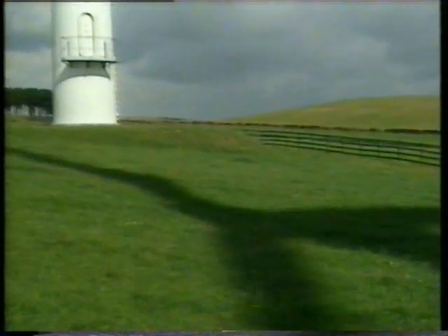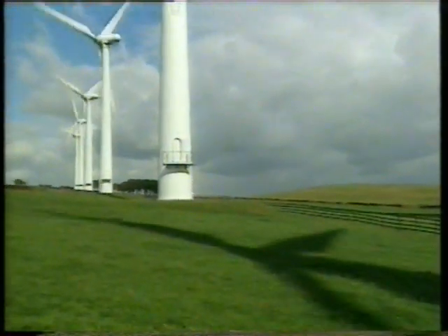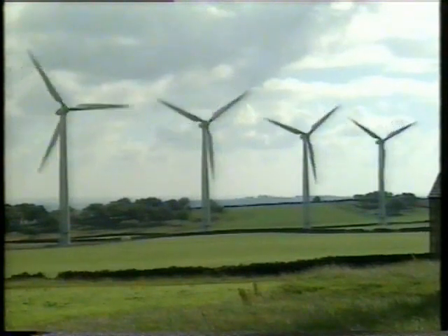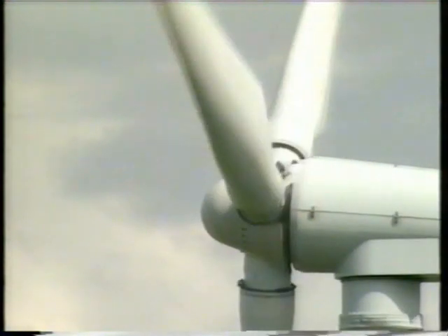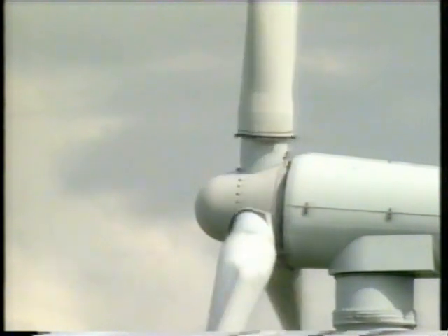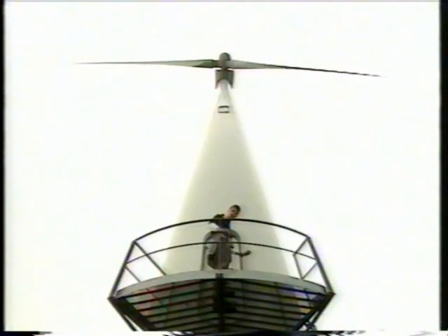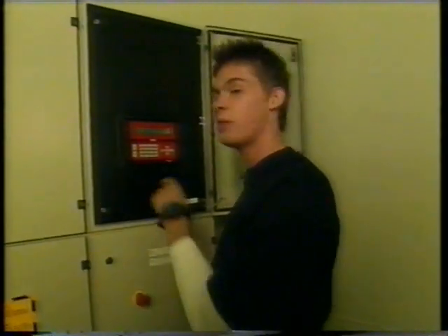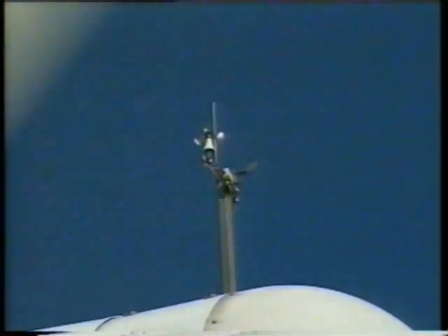As the wind blows, it pushes against the blades and they swing into action. Just like the other power stations, this turning motion moves magnets inside coils of wire at the top of the mast. When all of the turbines here at Royd Moor operate at full pelt, they produce enough electricity to meet the needs of 13,000 homes. Well, come on, let's go and have a look. What a letdown! It's just an empty space! Apart from this control panel, which monitors the instruments at the top of the tower and keeps the blades facing into the wind.